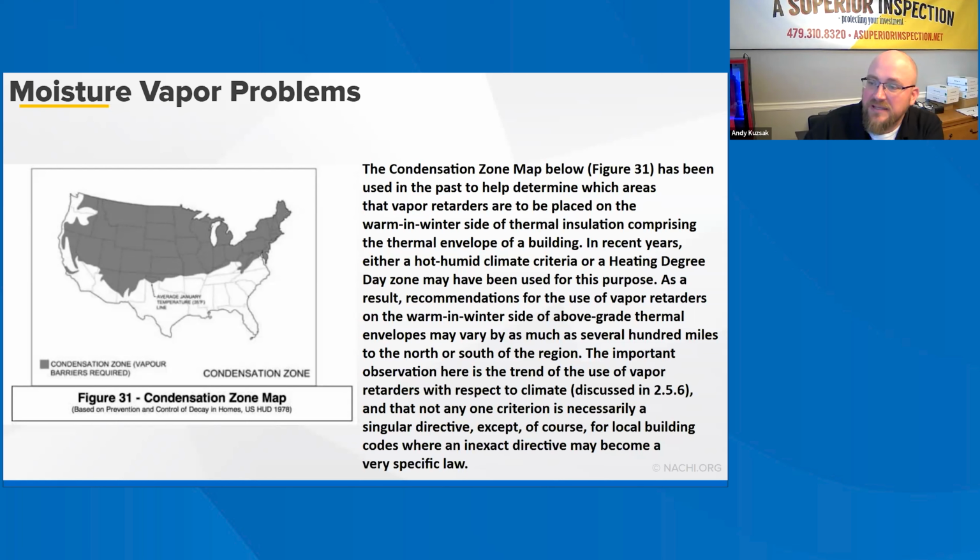Inspectors should consider documenting the existence of any supplemental dehumidification that is observed during an inspection. The presence of dehumidifier units may indicate the homeowner's concern about humidity or moisture. Supplemental dehumidification systems address indoor relative humidity by managing both built-in moisture in new houses, like water that dissipates from new concrete basements, and ongoing moisture loads in existing homes. Controlling ongoing moisture loads is especially important in areas with humid shoulder seasons, when the AC system will not operate for cooling, but indoor humidity must still be removed.